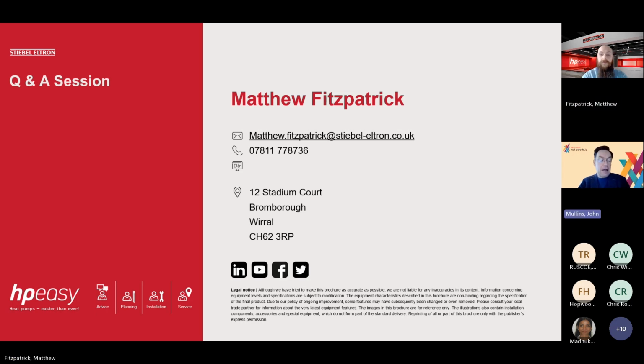Okay, that's fair. I've got one more question, and then we'll move to a few that are dropping into chat. Direct electric heating. The example you gave was the small commercial property using 100 litres of water. You go, right, we'll go for direct electric heating there. And then as the scale goes up, we get to 800-900 litres, and there's a case of there that a heat pump solution would work. Where's the cutoff point? Where do we start saying actually the volume where we're starting to move towards a heat pump being the right tool, and at lower volumes direct electric heating where we can save and not have to heat all the water in extensive pipework runs and things like that?